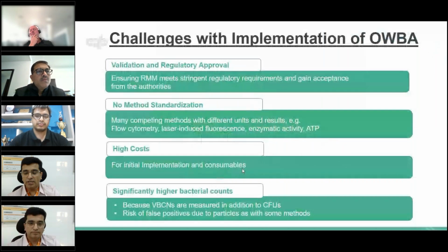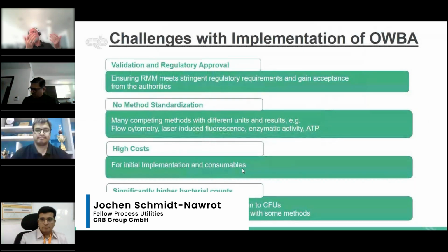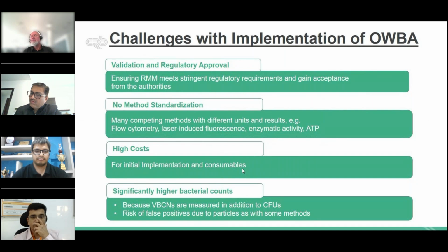Okay, we used to operate TOC measurements and conductivity measurements and have an online control of the situation in the systems. And the only last relevant time-consuming test method is the plate count bacteria test, which has to be done in the laboratory, and the result is given 5 days later. So when you have a microbiological problem, you know it 5 days later.